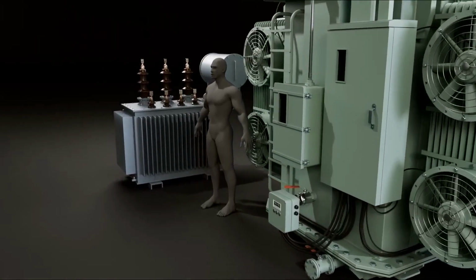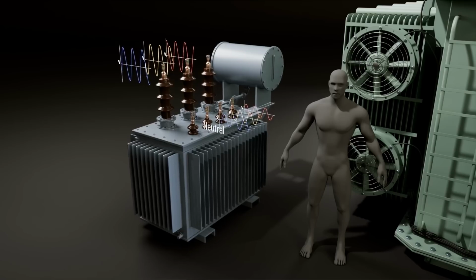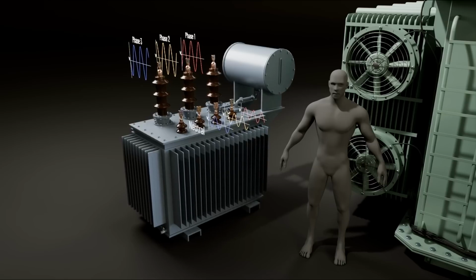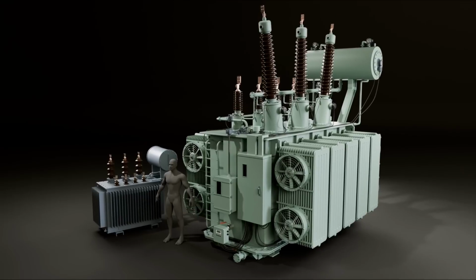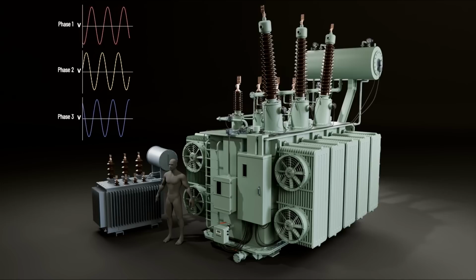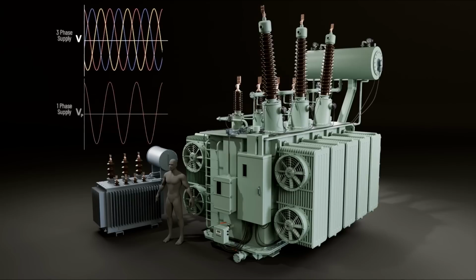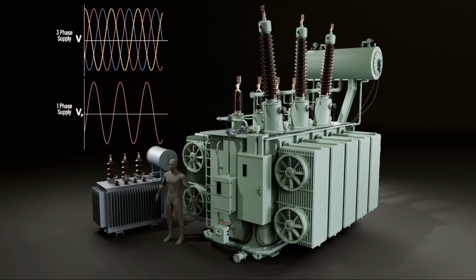In contrast, three-phase transformers are used for high-power applications. A three-phase transformer operates on a three-phase AC supply, which consists of three individual phases with a phase difference of 120 degrees between each phase. The power ratings of three-phase transformers can reach hundreds of MVA, depending on the specific transformer and its design. High power rating transformers typically work on a three-phase supply instead of a single-phase supply, because three-phase systems are more efficient for transmitting and distributing large amounts of power compared to a single phase.